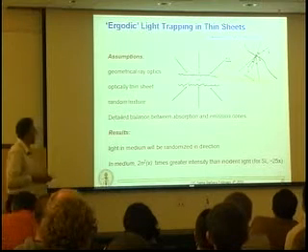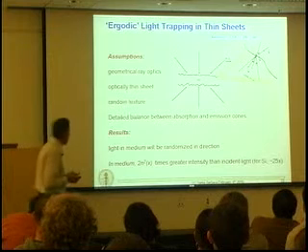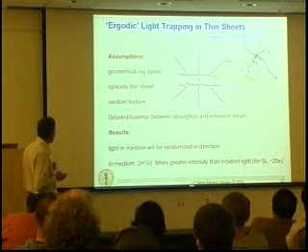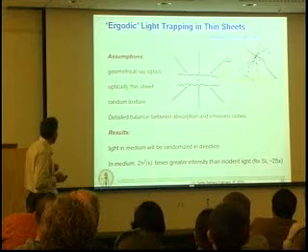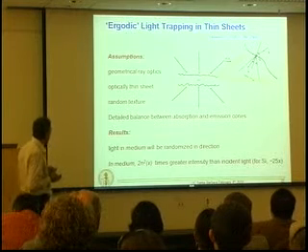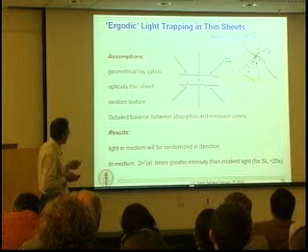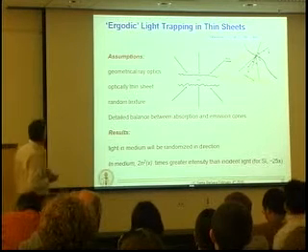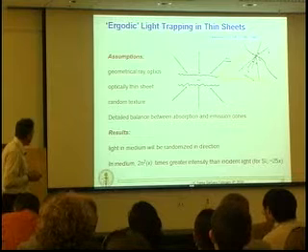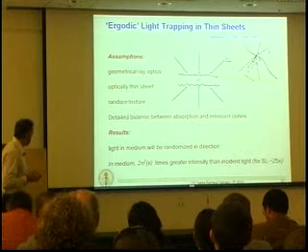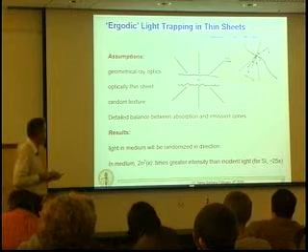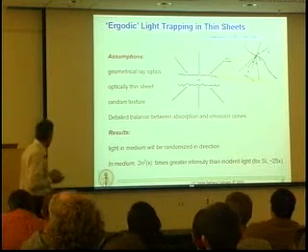And in fact, what were previously imagined limits to this process were defined by Eli Yablonovitch a number of years ago, and using a geometrical ray optics model, he posited that imagine you had a sheet of material that's almost dielectric, has low absorption, it's randomly textured on both surfaces, and if you do a detailed balance between the light absorption and light re-emission at this roughened surface, you come to the conclusion that for such a material in the ray optics limit, the intensity enhancement you could get inside this material, and therefore the absorption enhancement, which is proportional to the intensity, would be about 2 times the refractive index squared, or about a factor of 25, say, for silicon or for gallium arsenide, maybe a little bit more.